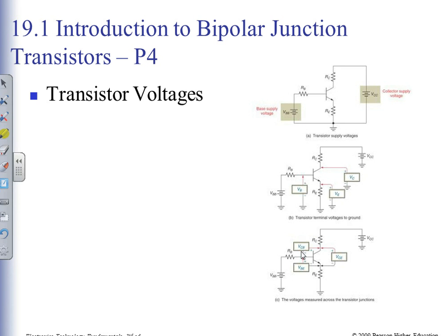This is showing voltage collector to base, voltage base to emitter, voltage collector to emitter, but it's showing it as capital letters, meaning it wants the DC voltage that's there. It doesn't want the AC component. If I write VB, then I have voltage that's base to ground, emitter to ground, collector to ground, is what I'm looking at.